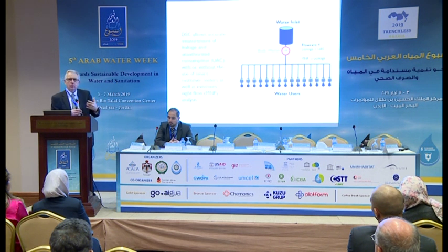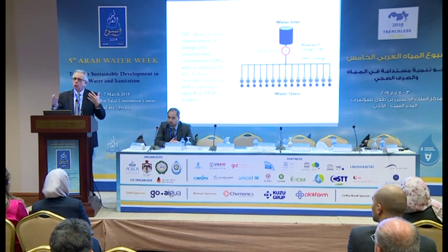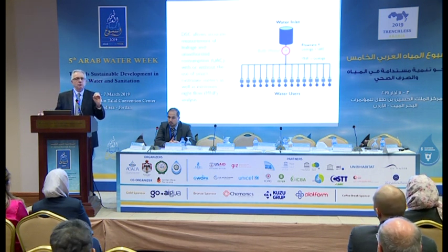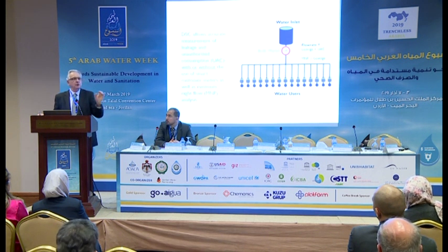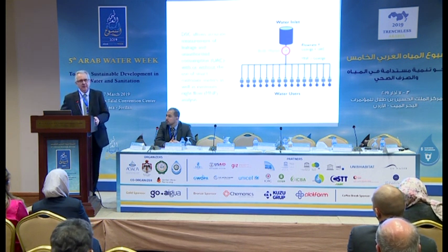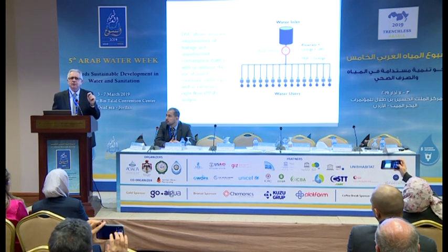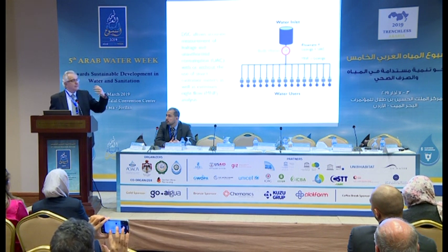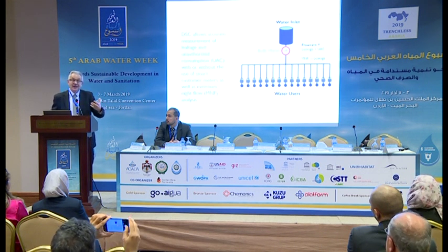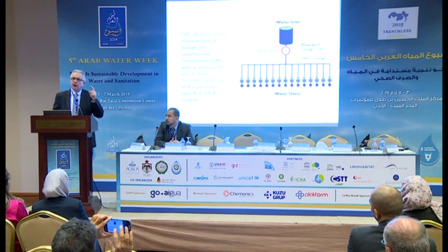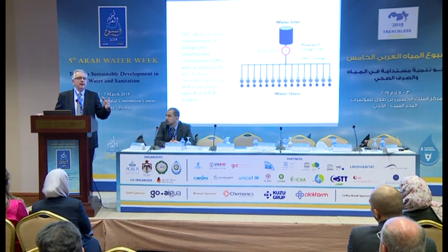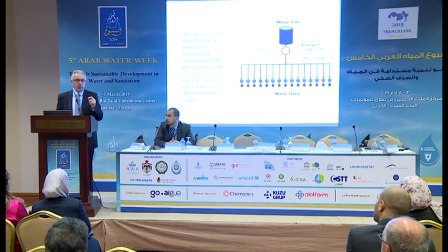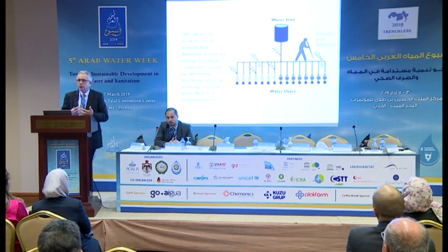UAC. So the water that goes through when the customer valves in that particular area are closed is equal to leakage plus whatever unauthorized consumption we have. If we don't have unauthorized consumption, that means the minimum night flow equals leakage. And this is information that we get additionally using downstream control that we don't have under intermittent conditions, because we don't have this particular flow pattern. What can we do with this?